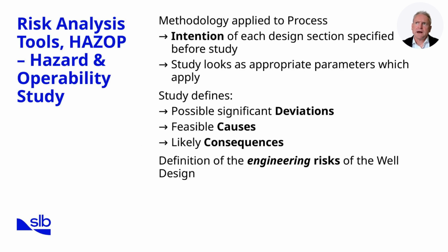The HAZOP, or Hazard and Operability Study, is one of the most structured and systematic approaches to identifying risks in drilling and process operations. The methodology begins by specifying the intention of each design section before the study starts. In other words, we clarify what the design is supposed to achieve so that deviations can be clearly identified. The study then looks at parameters that apply to the process. These might include flow, pressure, temperature, or mechanical conditions depending on the stage of the well design.